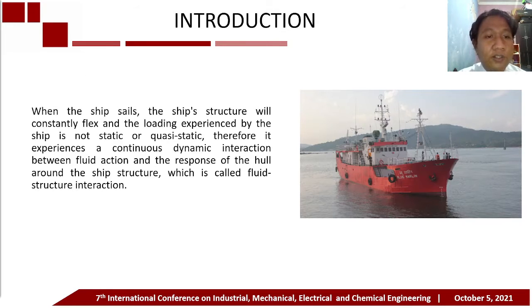When the ship sails, the ship structure will constantly flex and the loading experienced by the ship is not static or quasi-static. Therefore, it experiences a continued dynamic interaction between fluid action and hull response around the ship structure, which is called fluid structure interaction. This study focuses on a multiphysics simulation method for a typical passenger ship disaster scenario, showing the FSI model approach for ship collision events or grounding.